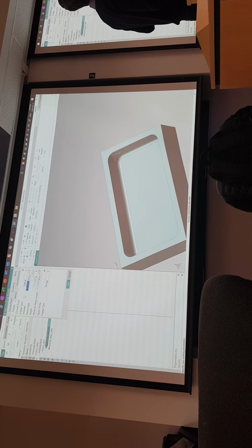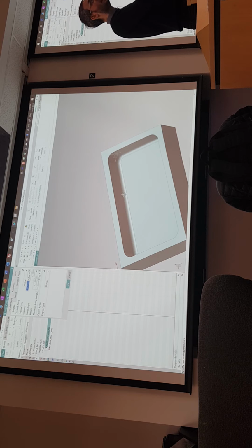And then for the non-cutting moves, in this case, I wanted to engage the workpiece with the helix, which is the equivalent of drilling a hole. You could use two tools. You could use a drill to drill a hole. Let's say you have 100 of these pockets. Maybe you don't want the end mill to do all the ramping. Maybe you already want to give it access, so you use a drill to drill 100 holes, and then you now have access to each pocket, and then the end mill just has to go into each hole and then start opening the pocket.